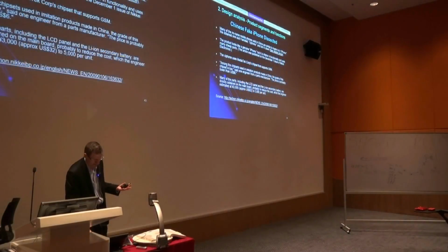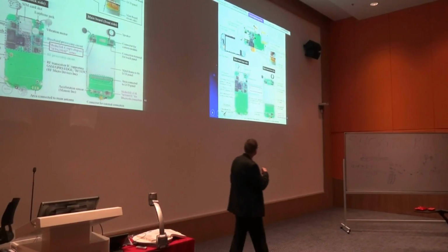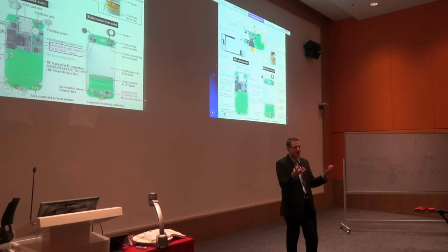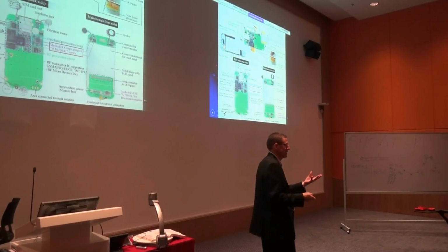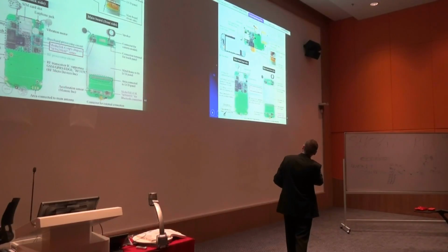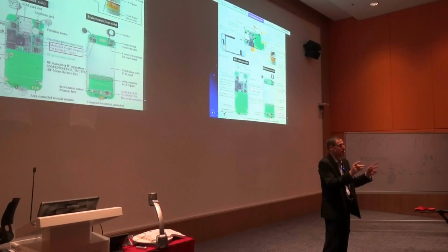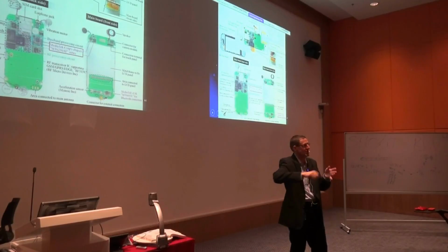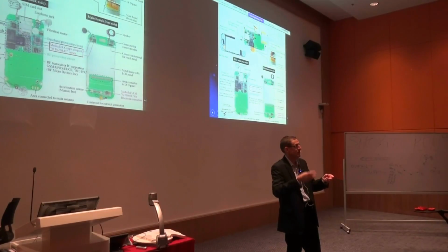Design analysis. Okay, so how many of you like the iPhone? You got an iPhone? Guess what? I bought some. I wanted to bring one into the lecture. I'll bring in a fake iPhone. It works. How do they make it cheaper? What they do is they solder the LCD panel directly to the main board. Soldered. So if you drop it, it comes apart, suddenly it doesn't work anymore. Whereas your iPhone that you have is screwed and fixed properly. Why would you solder it? Because it's cheaper.